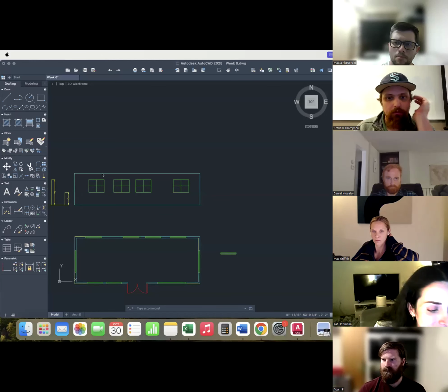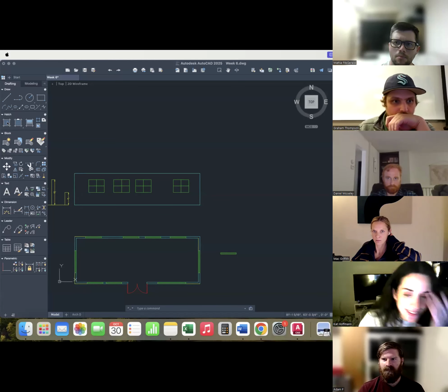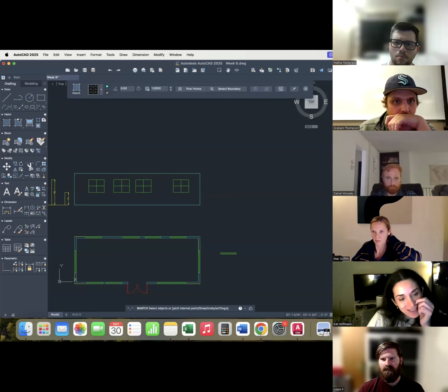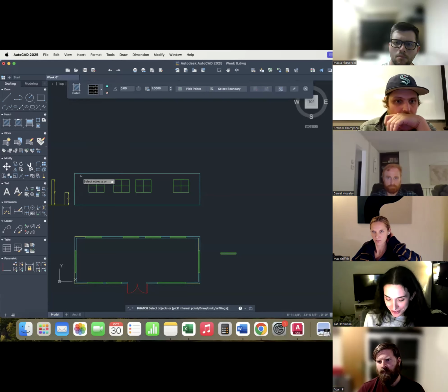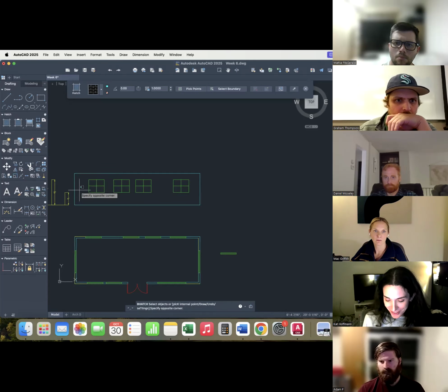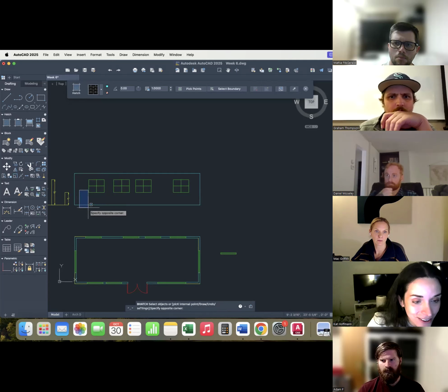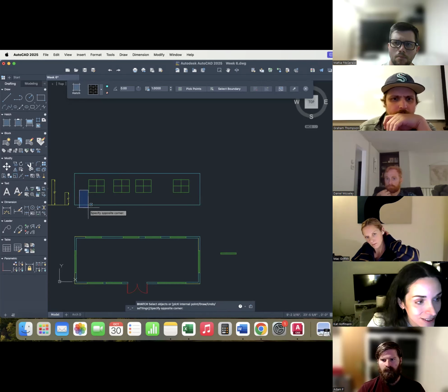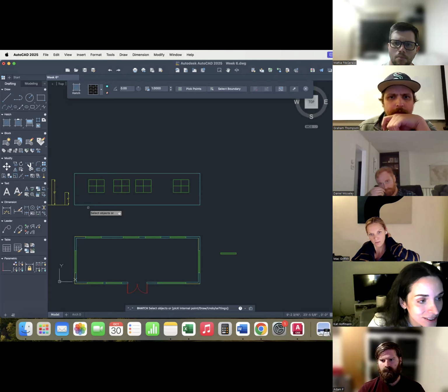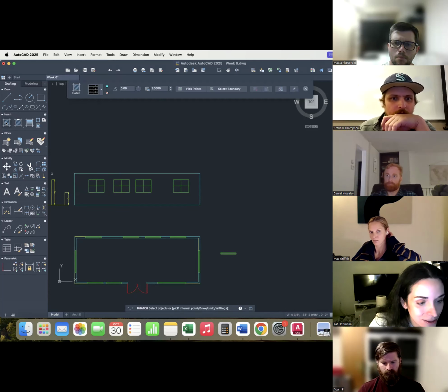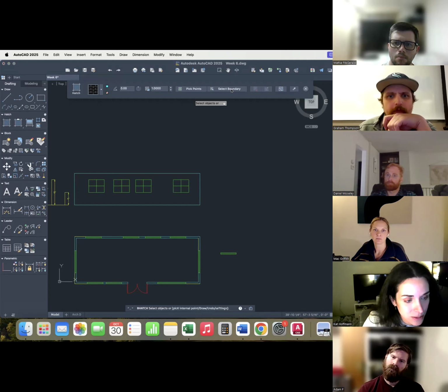Okay, so hatch, and then I got brick chosen here. So click right there. So when I click there, it's wanting you to select here. Hit escape. Right there it says select boundary. So right here, instead of select boundary, change that.